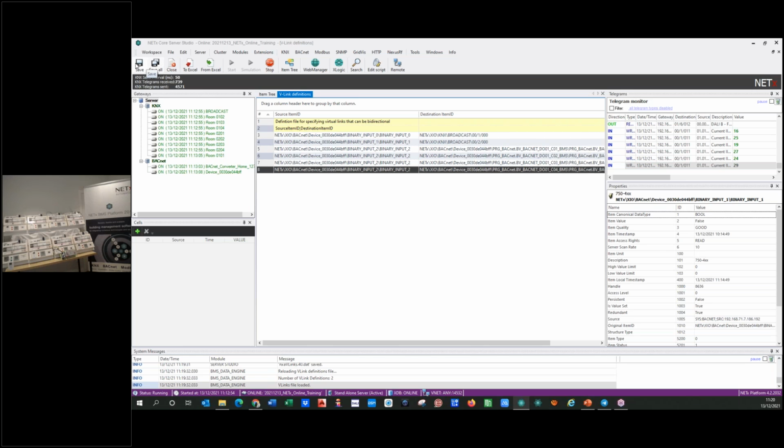So let's take a look if it works. I will show you directly. I just press save. I am not forced, as you can see, to restart the BMS, and I can just test it. I am going to activate the input number 0, and so you will see all the lights on. And when I release the cable, I have some cable for doing this test, you will see the lights off. I will do the same with the input number 1, that is the second, and you will hear the shutters going up and down when I press and release, and the third is for the BACnet object. So you will see now with an example.